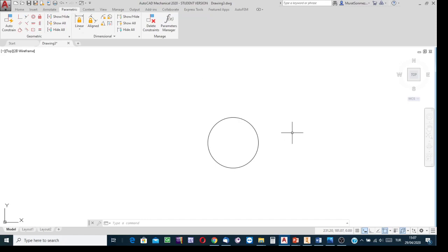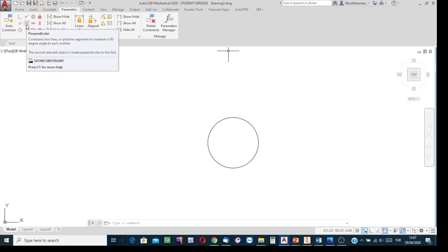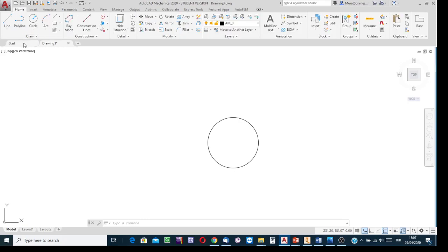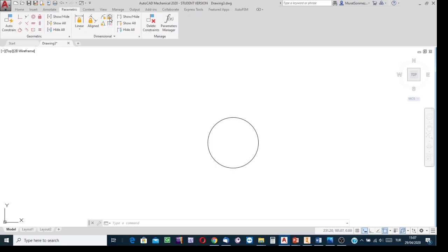Dimensional constraint, since I selected the modern method. But by the way, the modern sketching method is applicable in the 2D environment. After changing the mode from 2D to 3D, then you need to use the classical method. At least for today it is a must. I don't know whether in future the modern method will be applicable in the 3D environment as well. I don't know. Okay, Home ribbon, and then the Parametric ribbon, the diameter inputting button, indicate the circle, and then say that its size is 32.